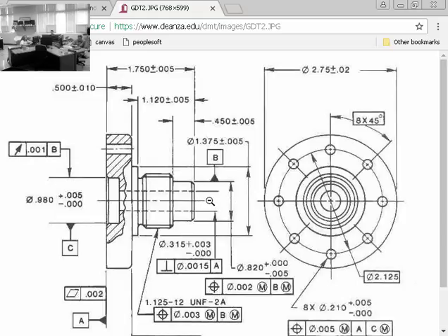So they may have been going for this surface, but in reality they're probably establishing this cylinder size as a datum. The easiest way to tell is to look at what they do feature control frame wise. So we won't go into that right now. That's a little bit above where we need to be at the moment. Yeah, it blows your mind when you start to see all the complexity of this stuff, but that's okay. We'll get there. We're just worried about the basics.